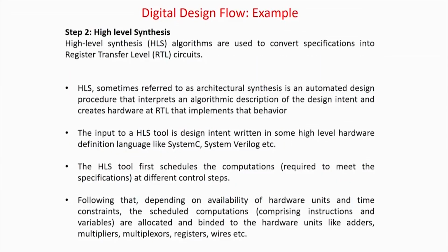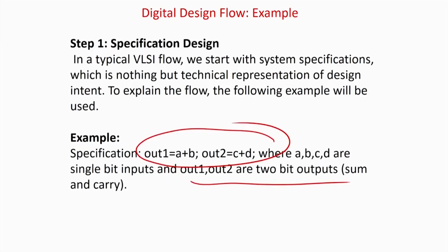Then the first step is called high level synthesis. Basically, somebody might have told you that you have 2 bits coming and you have to add them. It is a very simple specification here, so nothing much to think about, I can directly write this. But in a real case, the general specification is written in text, and 100 or 1000 man hours go into converting it into an implementable or technical specification.